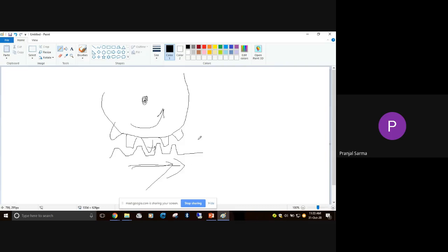That means if you can give motion to this rack, this straight line portion, I'm simply writing it like that, and this is the pinion, then rotational motion is being converted to the translation motion of this rack, or vice versa.